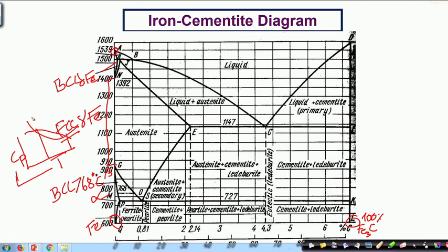So it is because of this variation of the two varieties of the crystal lattices of iron, pure iron, as a function of temperature, we see that if this is the BCC phase, and if this is the FCC phase, then we realize that in this temperature range, we see FCC to be stable and in this range and in this range the BCC phase to be stable, because Cp is lower, and accordingly the stability of the phase depends upon the contribution of Cp to enthalpy and entropy.